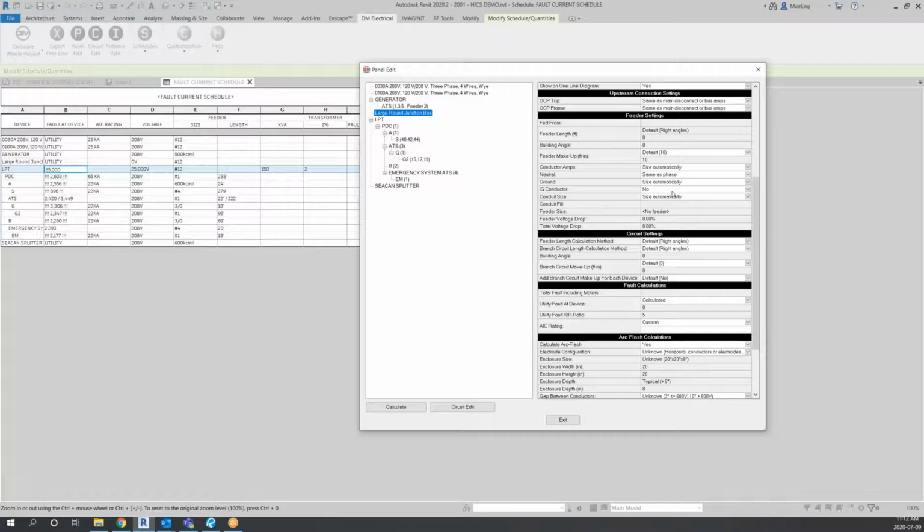There's another question. Any features in Design Master for AutoCAD that are not available in Revit yet? And I'll go ahead and just field that one for you. There's a lot that we can do in our AutoCAD software that is not in Revit. So for those of you who are using our AutoCAD software and are looking to transition, it's not going to be a straight transition. For example, all of the feeder and service calculation stuff that we've done, the multifamily dwelling things, none of that is available in Revit. Revit has some of that built in, but it's not to the degree and sophistication that we've got done in our AutoCAD software. That's the biggest one.